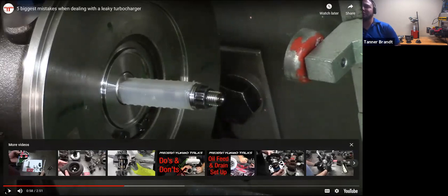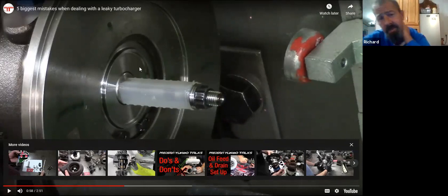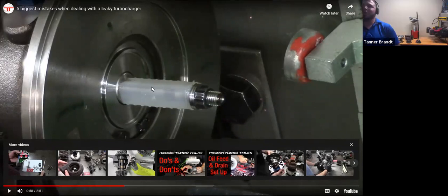So what he's done so far, this is set up now. This is the flinger right here, like we talked about. There's no seal on it at the moment, so no metal ring on it at all. And what he's going to do is turn the oil on, do it here in a second, and I'll show you that. And you're going to see that no oil comes out of that, even without a ring.